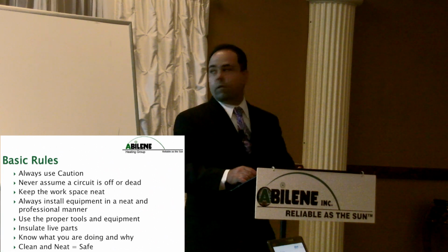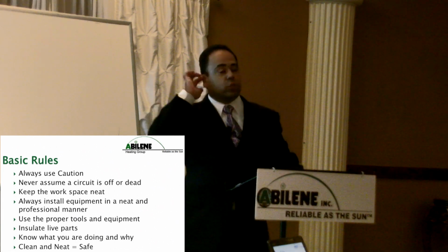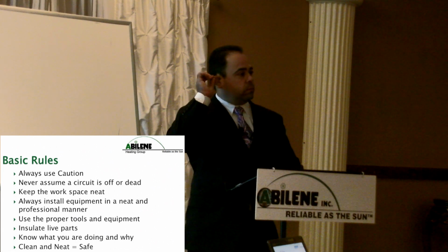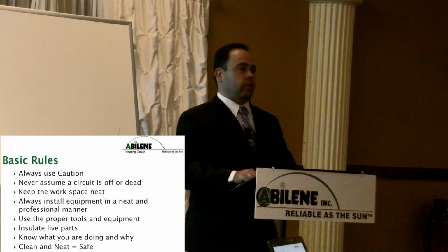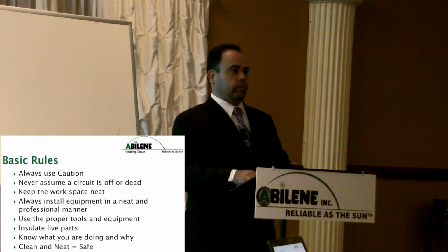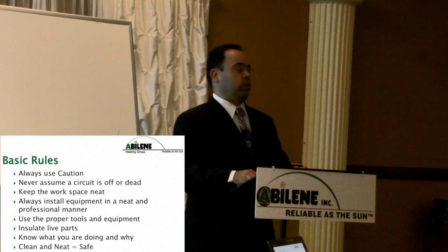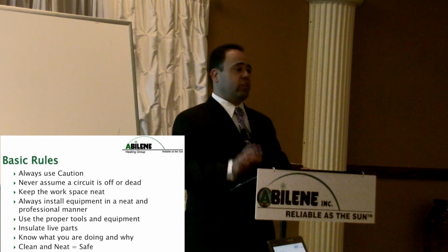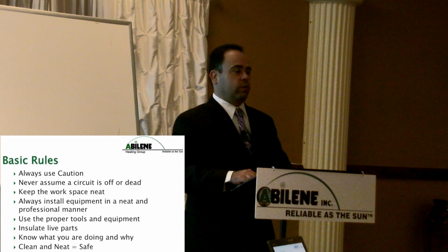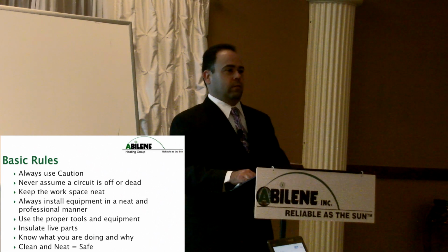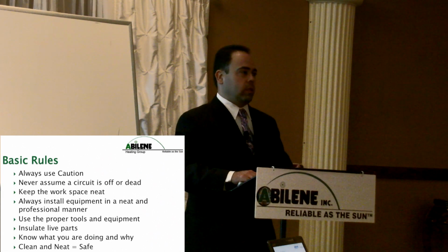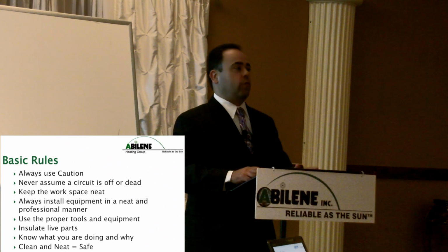Just be careful. Be very careful. Never assume a circuit is off or dead. Always test it first before you touch it. If you don't have a tester, go get one. All right? If you can't get one, ask somebody for it. If somebody says, yeah, don't worry, I checked it, it's off, check it again. Okay? Always test it first. Never assume that it's off or dead.